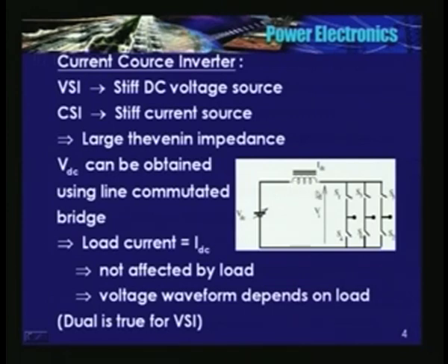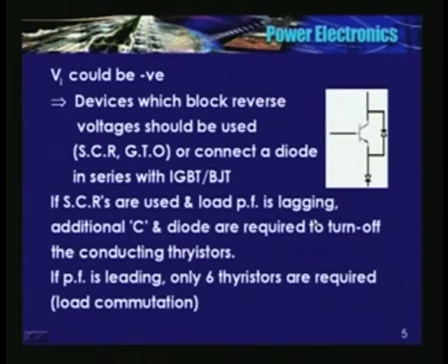Assume that I am connecting this to a three-phase AC source. We had connected a DC link inductor to filter out the current, and the load can be equivalent to the back EMF of a DC machine. Of course, the direction of current of these devices should be opposite. So almost the same operation we have here. At any given time, only two devices are conducting. One phase is open.